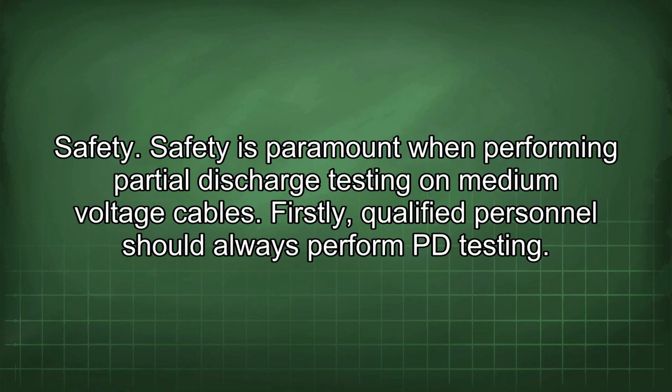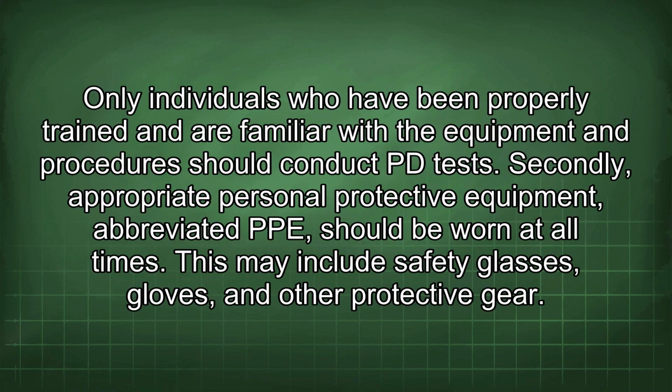Safety. Safety is paramount when performing partial discharge testing on medium voltage cables. Firstly, qualified personnel should always perform PD testing. Only individuals who have been properly trained and are familiar with the equipment and procedures should conduct PD tests. Secondly, appropriate personal protective equipment, abbreviated PPE, should be worn at all times. This may include safety glasses, gloves, and other protective gear.